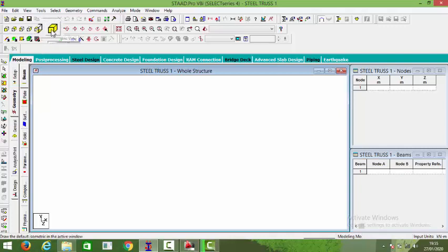If you put this in view from Y, taking it to a 2-dimensional view, you see your UCS. Let me put it on isometric again. You see your UCS is in 3D, but if you put it on view from Y, your UCS will change to 2D. Everything in this horizontal plane is X, and that's where you have your base of 1.5 in 6 places.